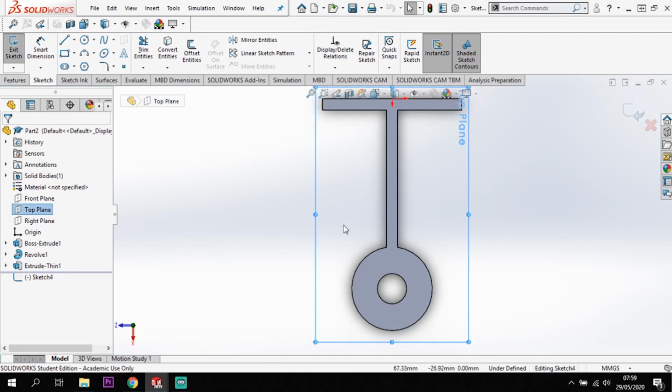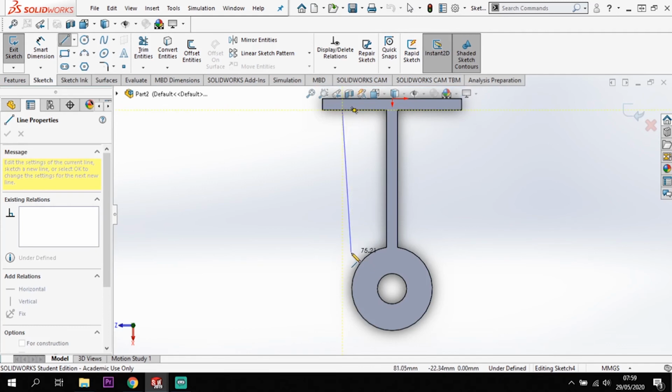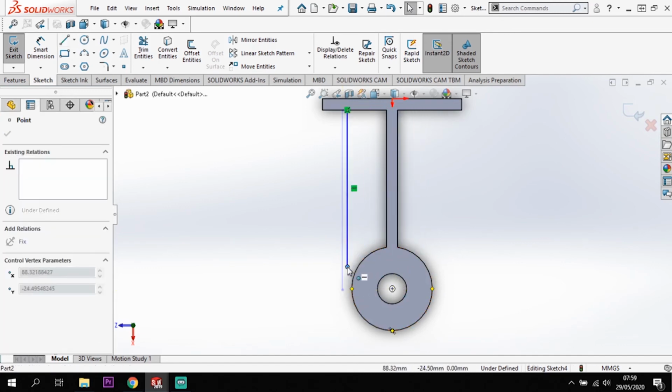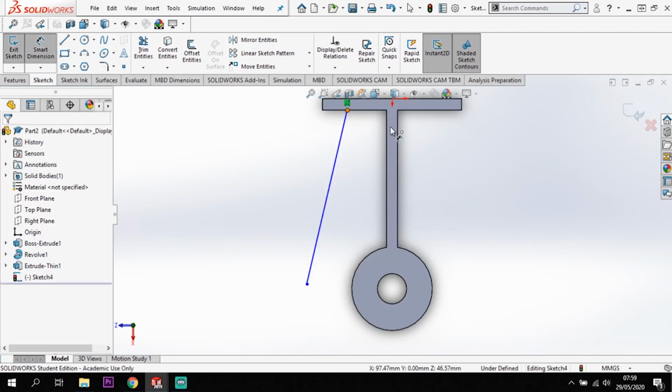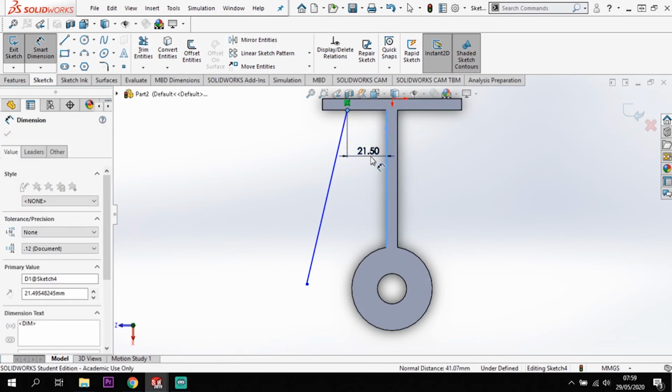and I'm going to create a line. So if I go to my line tool, I'm going to come from here and across here, like so. Now at the moment, let's get rid of that. At the moment, this isn't connected to anything. Now we will get it connected to something in a moment, but first of all I'm just going to set this distance out from there to there, which is going to be 25 mm.